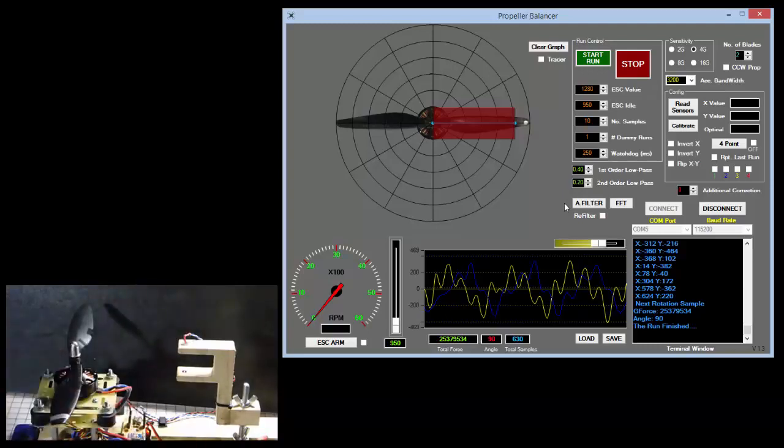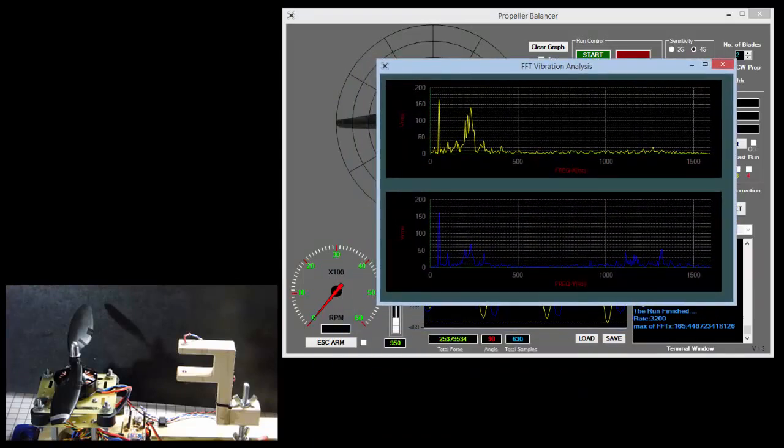So the way that I will start is, having taken samples, I will bring on my FFT, and you can see right away that we have a couple of major imbalances according to our spectrum graph here. The first one is actually pretty high, at around 165 at 50 Hertz, and there seems to be another one at 140 at 231 Hertz. Now this is probably like bearing, or it might be due to your setup with the rig. The net of it is there are two imbalances here, and what we need to do is isolate every single one of them and try to eliminate them.